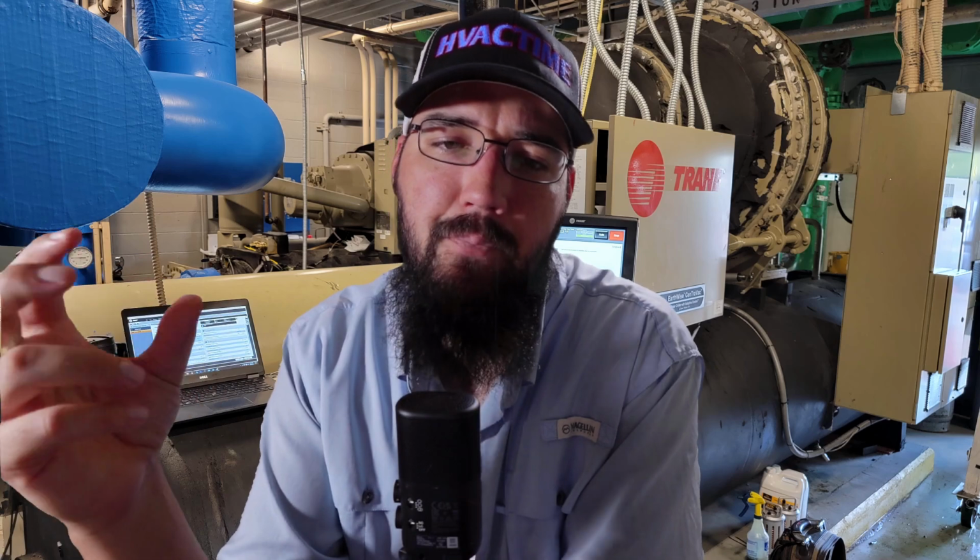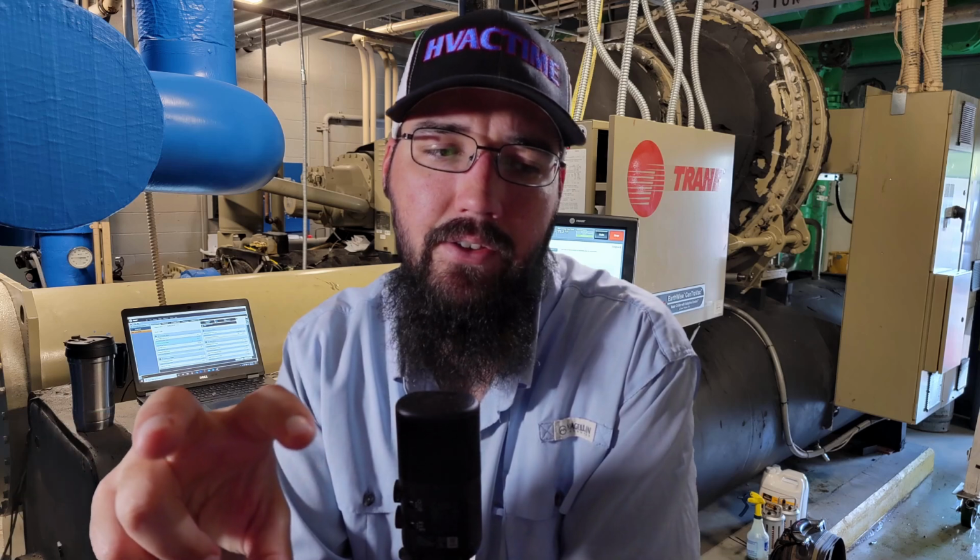so that we can maintain proper oil levels. So if you've got those types of systems with a shell and tube DX or a brazed plate, something like that, tube in tube, and you're having issues with oil stacking and you're not getting all that oil to come back, not only will you see it in low oil levels in general inside your reservoirs, but you'll also see it in your approach values.